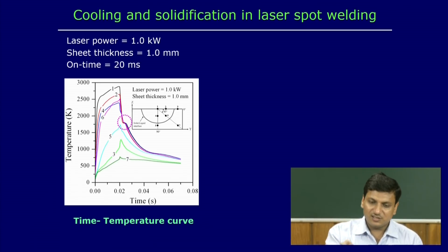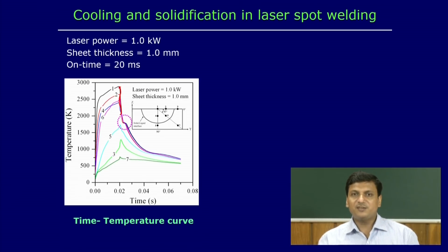So, here you can see the temperature reaching the peak and gradually decreasing. In the marked space you can see a kind of hump, which represents a phase transformation over the temperature range. That means the transformation from the liquid phase to the solid phase happens over a narrow range of temperature in the case of an alloy.